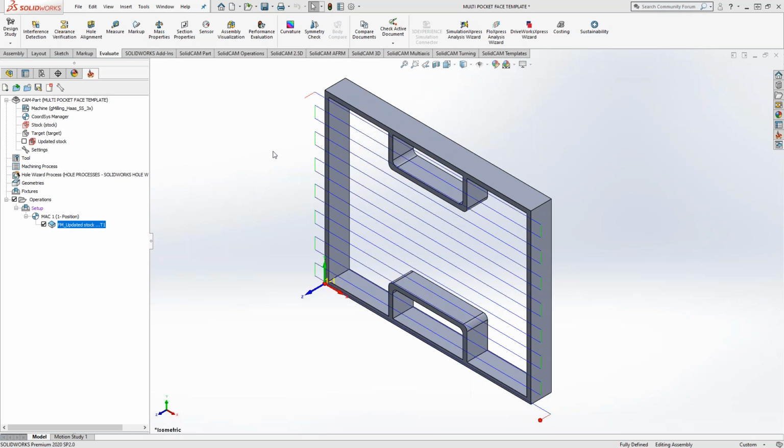Well, there's a lot of ways where you can get your programming to always follow the same mode. Use this tool with this offset, with these feeds and speeds. You can get the templates to record all that information for you, and then all it is is just load and calculate. Where I'll use a lot of process templates is when you're doing tapping. So you get your spot drill, drill, tap, or a spot drill, drill, ream.